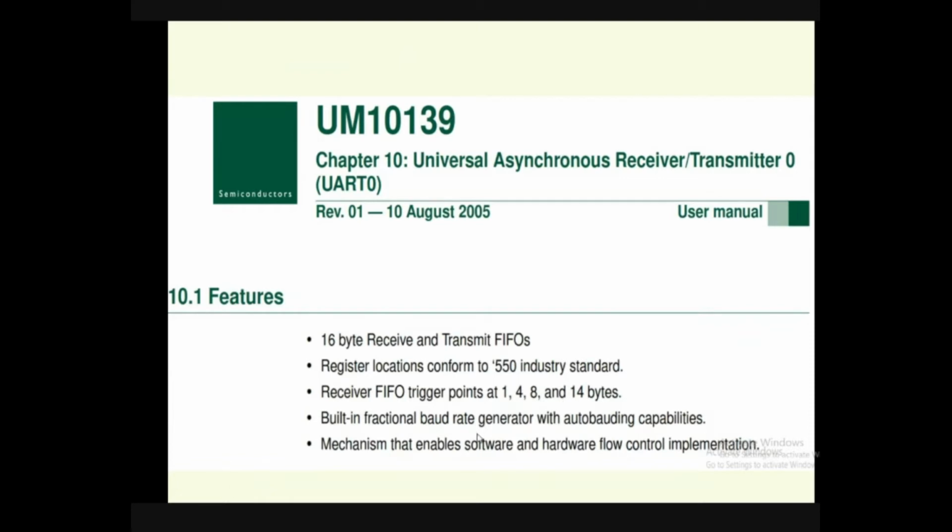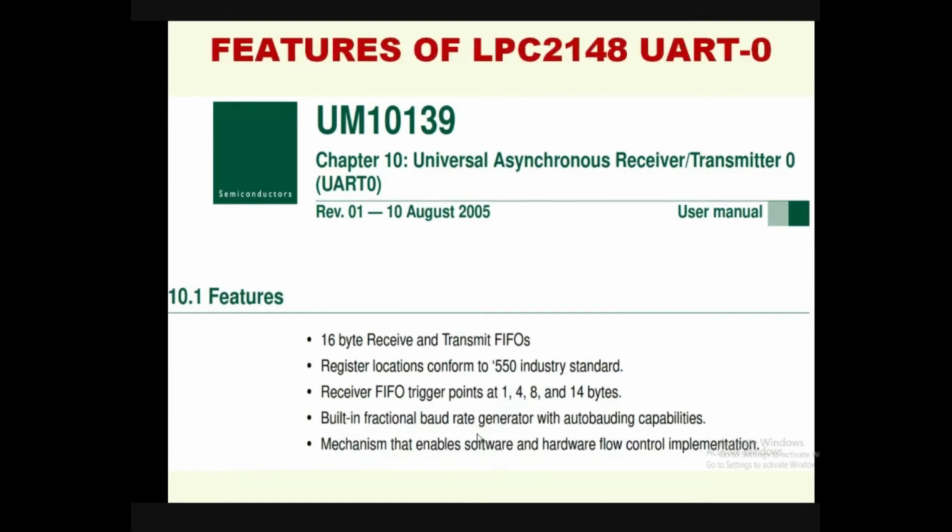It has a built-in fractional baud rate generator with auto bauding capabilities. So automatic baud rate generation is also possible in the LPC2148 microcontroller. And there's a mechanism that enables software and hardware flow control implementation. Okay, so these are the simple features of UART in the LPC2148 microcontroller.